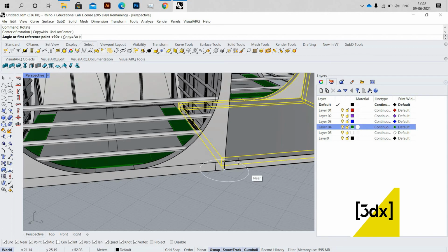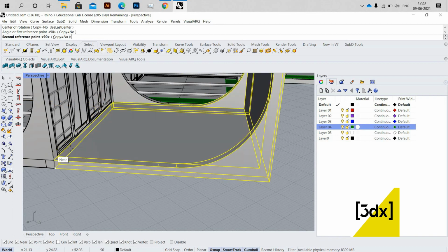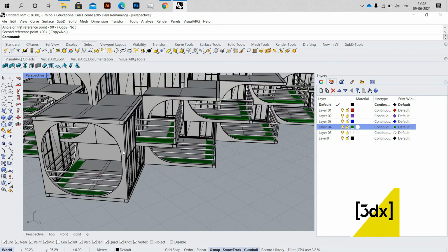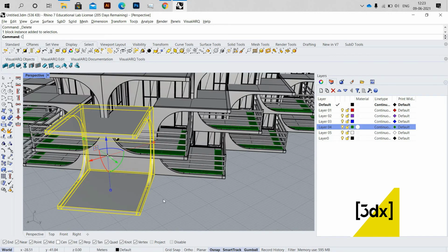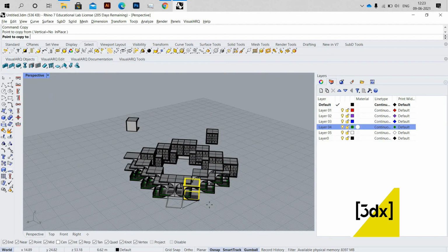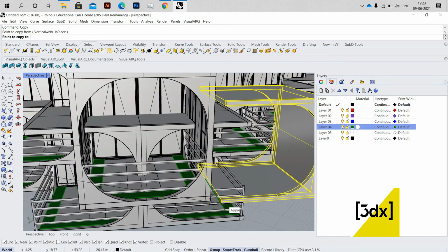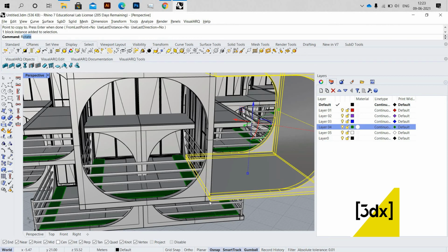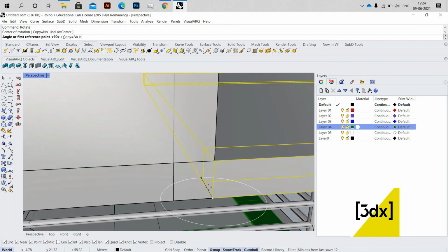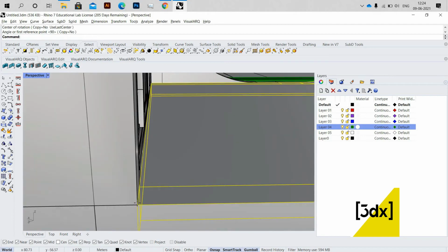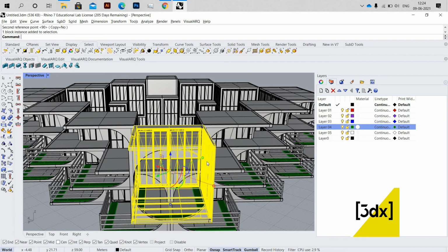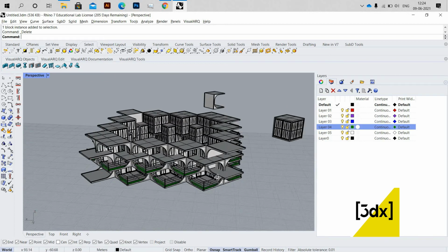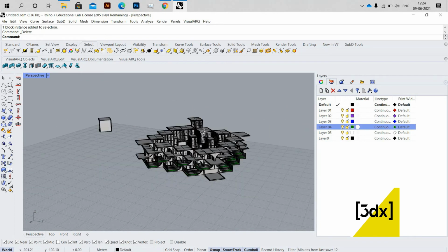Now I'm using the rotate command. So it has been rotated, yeah. So I'm deleting this. So I'm going to copy again, and I'm going to do it on the upper intersection. So we have to do this on all the four sides, not all four, top and bottom. It's intermittent: in one direction it will be at the top and in another direction it will be at the bottom. So when you create a pattern like this, you will get to know, and you can also try your own pattern with this block edit, with this block command. So this is what I need.